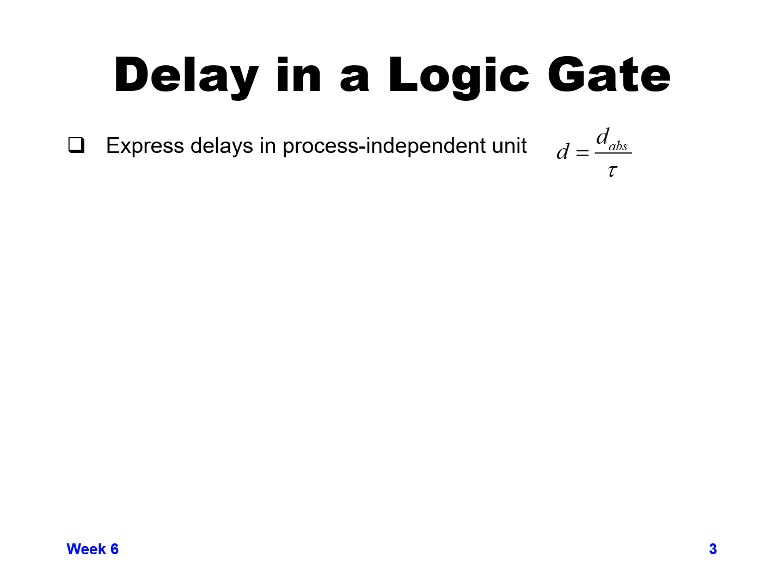for a given process. So for example, I said several foils ago that the delay through a minimum size inverter on a given process with no load on it has a delay of 3 RC. So no matter what process technology you're on, the delay through a minimum size inverter with no load is 3 RC.